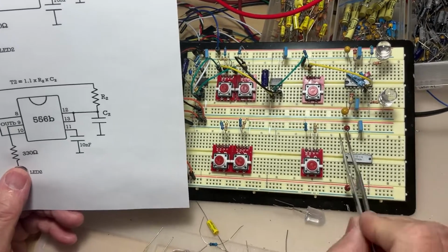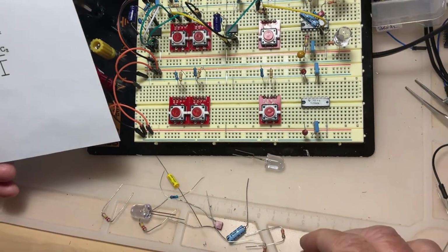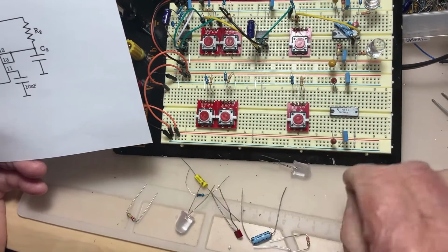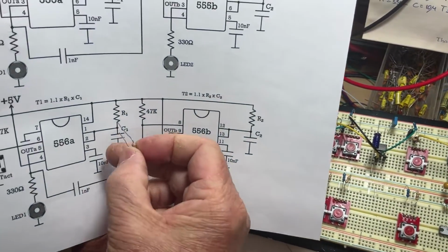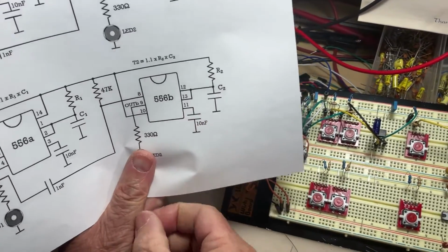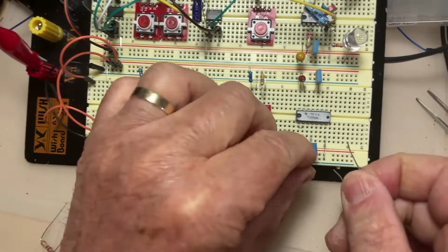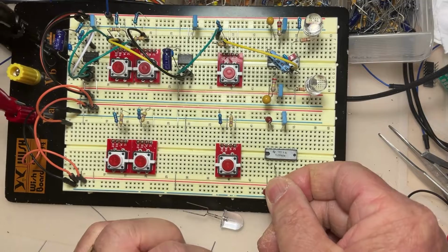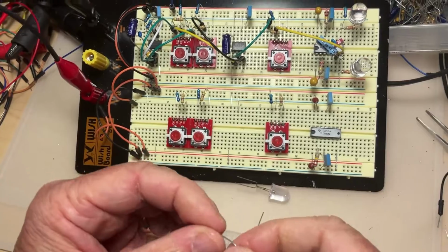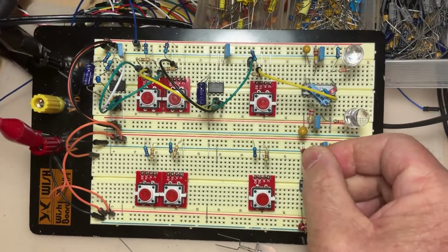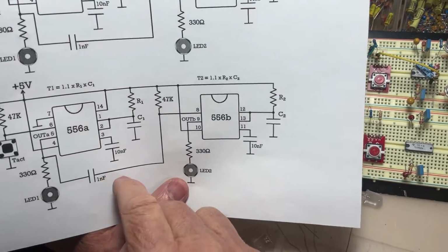So once you put the two capacitors, next thing you should do is to put the two resistors, 220 kilo ohm each. So one of them goes, as you can see here, between the pin 1 or 2 to the positive. It's very easy, like this. And the other one goes pin 12 or 13 to the positive, just like that. Okay. So we've made a lot of connections already.